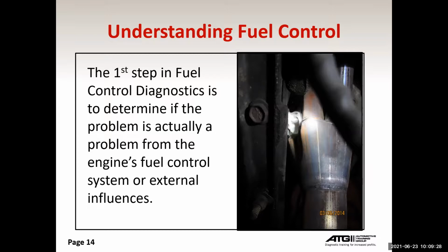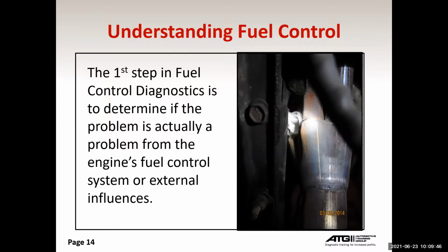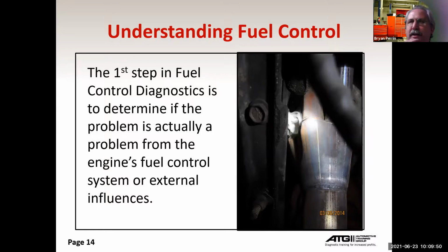Honda's crack pretty regularly. Those are available aftermarket. Magnaflow sells them that are approved for California. Walker might have them also. So you don't have to get it from the dealer. They are available aftermarket, but it's still a pricey repair, and it's a common failure right by the O2 sensor there. Yeah, exactly. Thank you so much for that input. Not a problem.